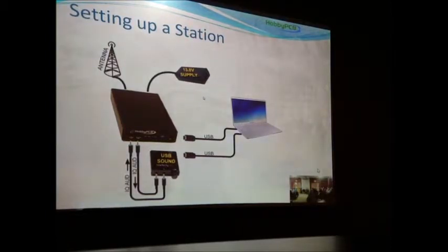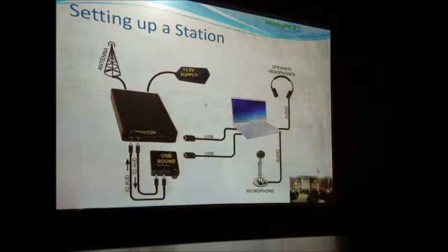But if you want to actually have a QSO, you need a microphone on the computer, and I'm not actually sure you can hook a D104 up to a computer, and then some speakers or headphones. Now, it might be possible to use the speaker and microphone that are in the laptop, but I think you'll find that if you attempt that, you'll very soon want to have some sort of microphone and audio that's dedicated to ham radio. So that's where we get sort of 2 sound devices that are needed to do this. One for the audio in and out of the computer, and one to drive the radio.